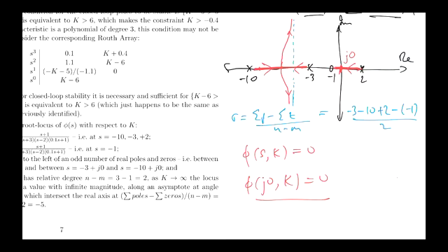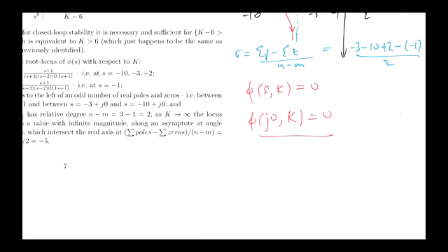Right? More generally, when you're trying to find where the root locus crosses the imaginary axis, all right, you need to use the fact that we'll be looking for an omega and a k that makes the characteristic polynomial equal to 0. So there are two unknowns, the frequency and k. It just happened in this example that we knew what the frequency was, 0, right?